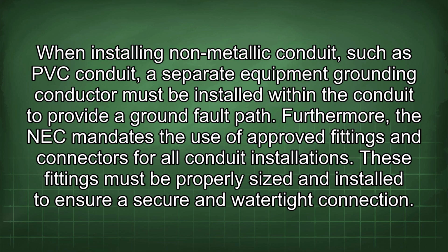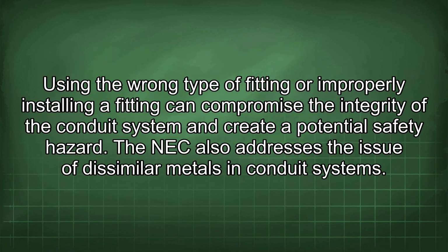Furthermore, the NEC mandates the use of approved fittings and connectors for all conduit installations. These fittings must be properly sized and installed to ensure a secure and watertight connection. Using the wrong type of fitting or improperly installing a fitting can compromise the integrity of the conduit system and create a potential safety hazard. The NEC also addresses the issue of dissimilar metals in conduit systems.